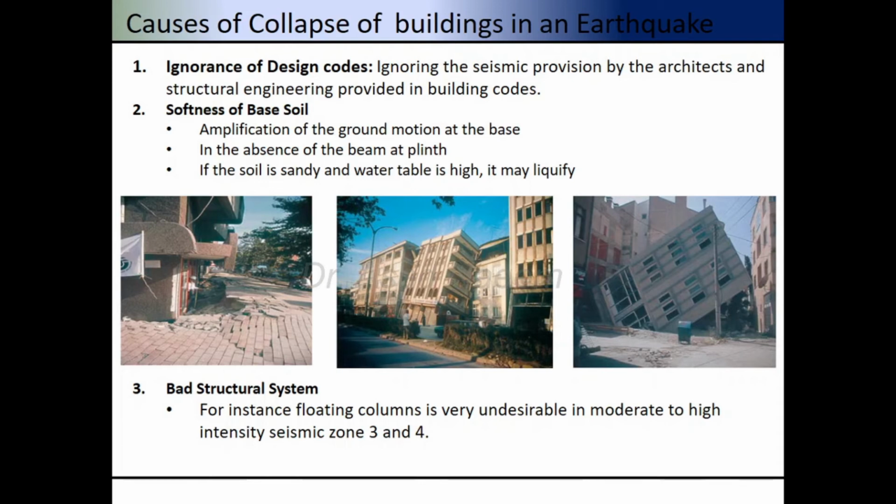Softness of base soil. The investigation of soil is very important and very essential in case of design of building structures in a high seismic zone. Earthquake can cause the amplification of ground motion at the base. In the absence of the plinth beam, it can cause a differential settlement. And if the soil is sandy or the water table is high, it may also liquefy.